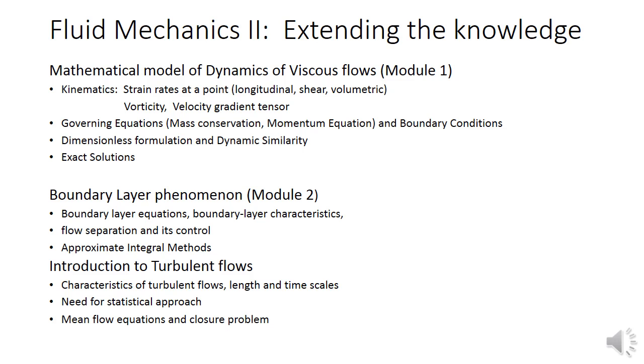So mass conservation, momentum equation, and of course the equations need to be supplemented with proper boundary conditions. Boundary conditions at this moment you can think of as typical conditions at fluid interfaces with other types of media like solids, like gases, even some other immiscible fluid. A liquid can have three types of interfaces: an interface with a solid, an interface with a gas, and an interface with another liquid which is not miscible.